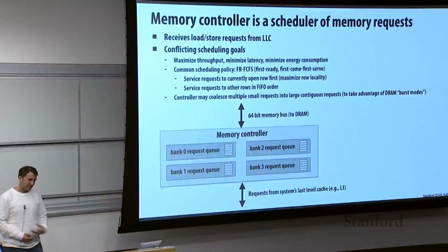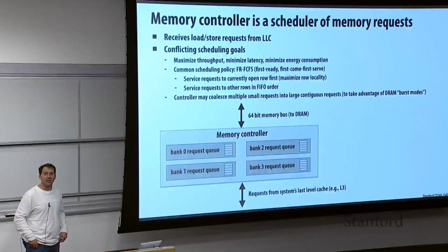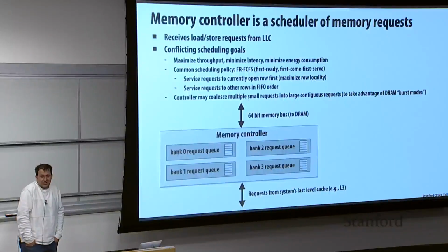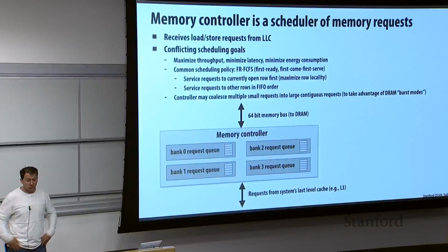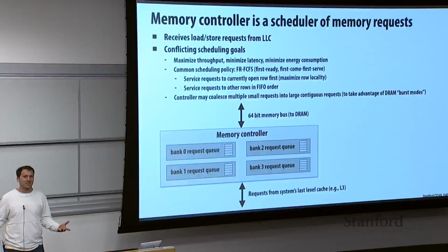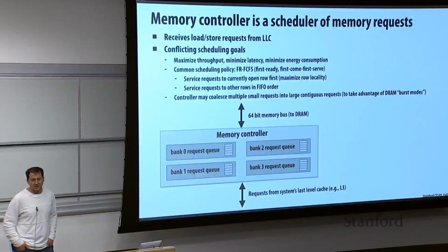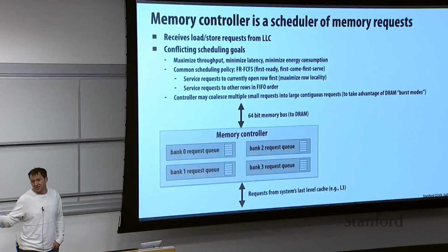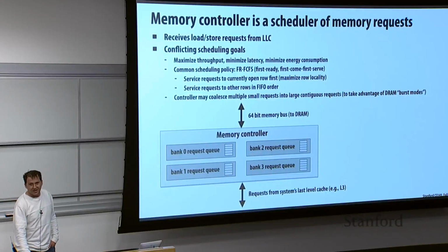So they took the complexity out of the processor and basically shoved it in the memory controller, which is getting requests from like 16 cores or 32 hyperthreads, and is trying to figure out how to reorder all of these requests from different processes to maximize pin utilization of the DRAM bus. Or energy. You're actually trying to minimize energy too.